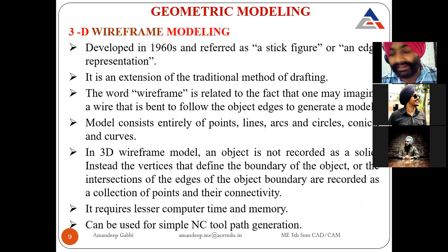It requires less computer time and memory. When you want to save a particular 3D figure in the wireframe model, it requires less space as compared to the solid and surface model. It can be used for simple NC tool path generation.